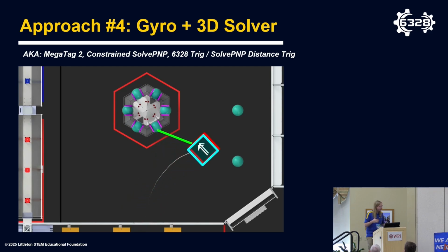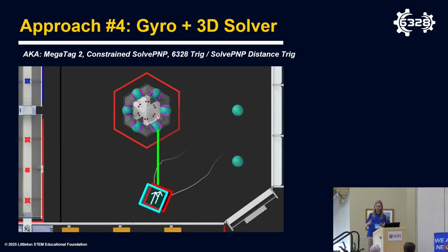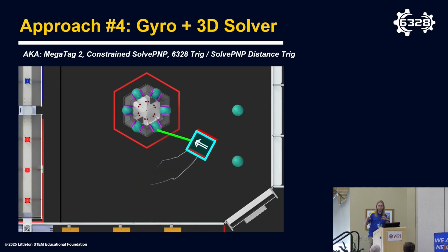And this class of algorithms, it's becoming increasingly popular. It is still not the be-all, end-all by any stretch, though. In particular, it still requires a very accurate gyro, which can introduce significant errors if that's not handled properly. And the accuracy is sometimes very poor when in motion if you don't handle latency properly. This is particularly a challenge for Limelight that's trying to do this algorithm on a coprocessor versus on the Rio, so there's some additional latency. They're working on how to compensate for that.